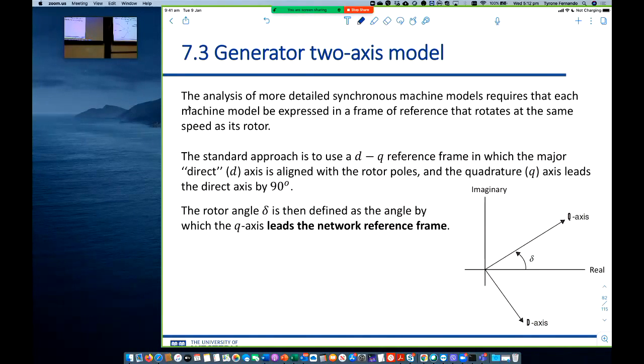So that's a frame of reference where I have drawn the real axis and imaginary axis, and that frame of reference actually rotates at speed omega, because we are representing omega t plus a phase angle, and that phase angle is what we represent as a phasor. So the imaginary and real axes are rotating at angular frequency omega.